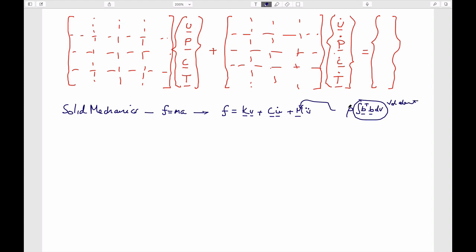So multiplying the volume of the element by the density of the element gives its mass, right? So if you're shaking it, this is the inertial resistance. We'll only deal with the steady state part, the non-inertial part. If we were to write this out, we would call this K solid mechanics, so this would be Ks. It operates on displacements, and there are no terms that operate on damping because we're going to ignore it, and there is no way to incorporate the acceleration term in this.